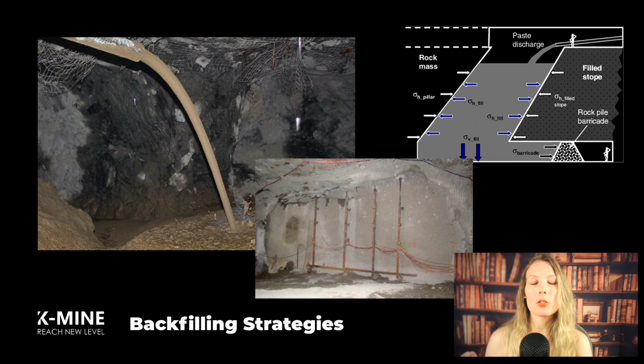Incorporating backfill parameters into stope design calculations can enable larger stopes to be extracted without increasing the risk of wall failure. A combined approach using geostatistical modeling, stability methods, and economic analysis is recommended for optimizing stope design.